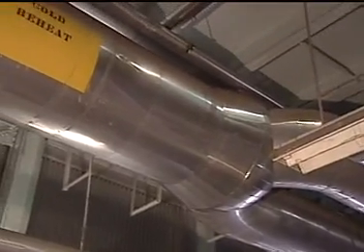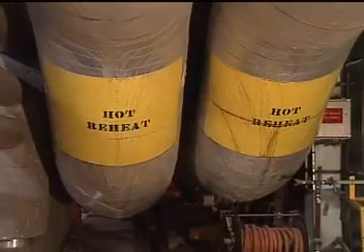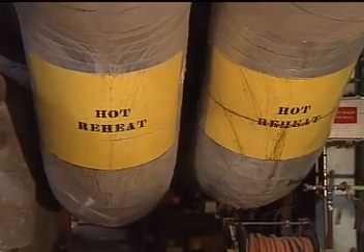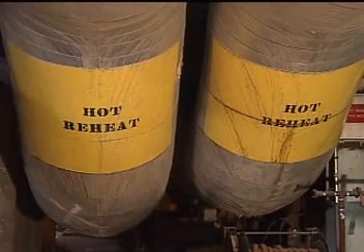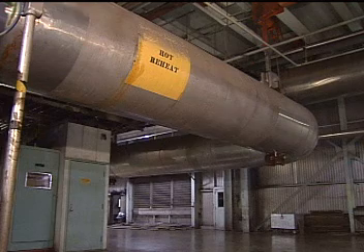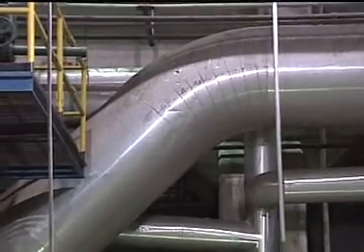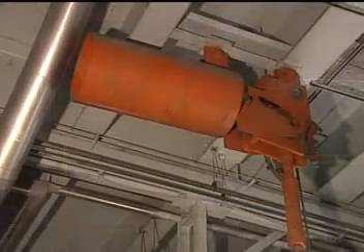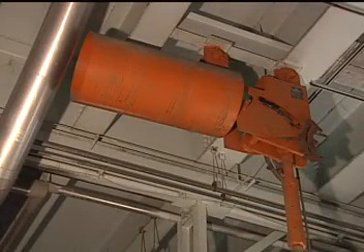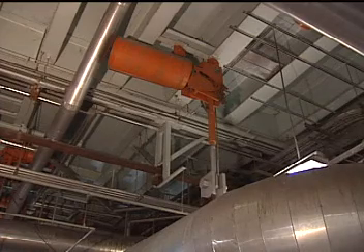As with any steam system, the piping is a critical component of a reheat steam system. Like most steam system piping, it's large, well-insulated piping that's designed to contain and direct the flow of steam. Of course, temperature changes will cause the piping material to expand or contract. So to handle these changes, the piping has expansion loops and bends that let the piping expand and contract without damage. In addition, pipe hangers and supports both support the piping and allow for some movement during expansion and contraction of the piping material.